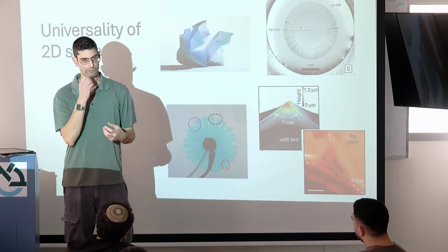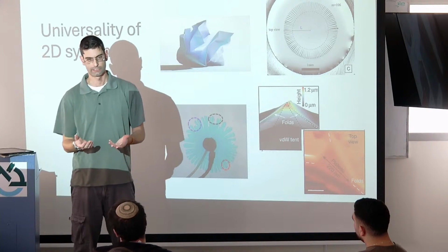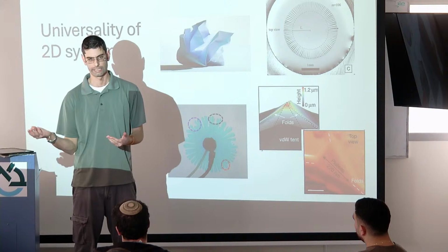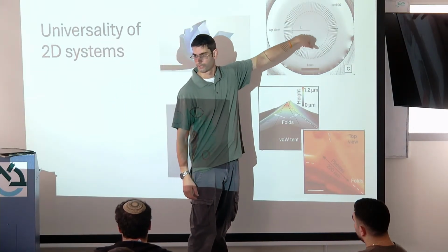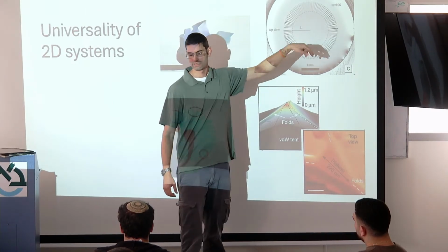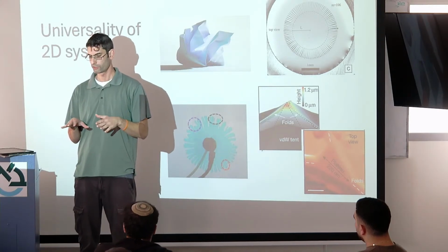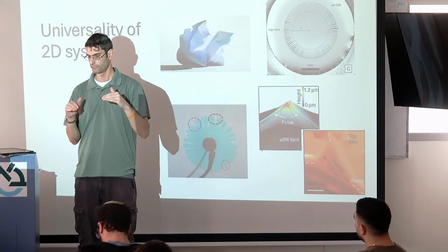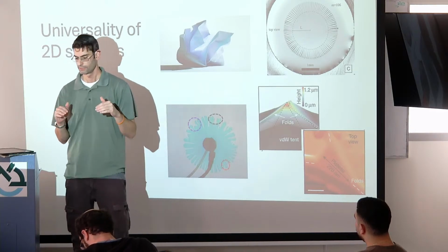Sorry, you get an unstable solution. Then you fix the unstable solution, and what sets the new energy scale is the term that you neglected. So you have to pay a little bit of bending energy by creating these wrinkles. And basically the idea is that it's like a Ginzburg-Landau instability. You have an unstable solution, an unstable mode, and the mode will grow until the bending energy precisely compensates for the stretching energy.